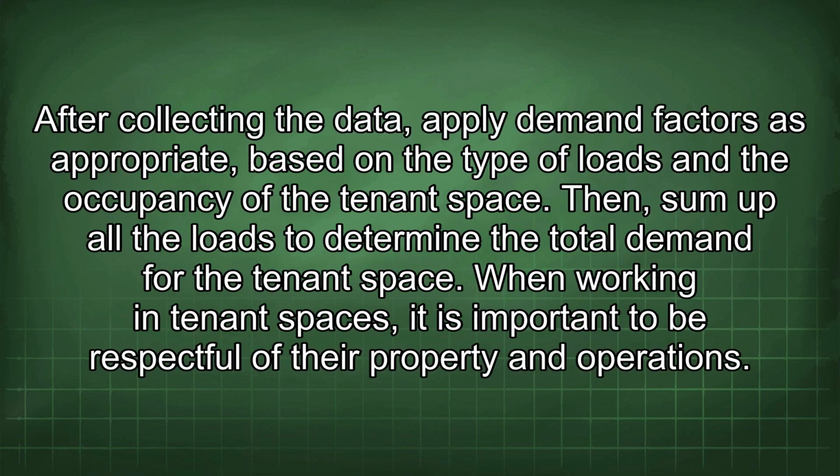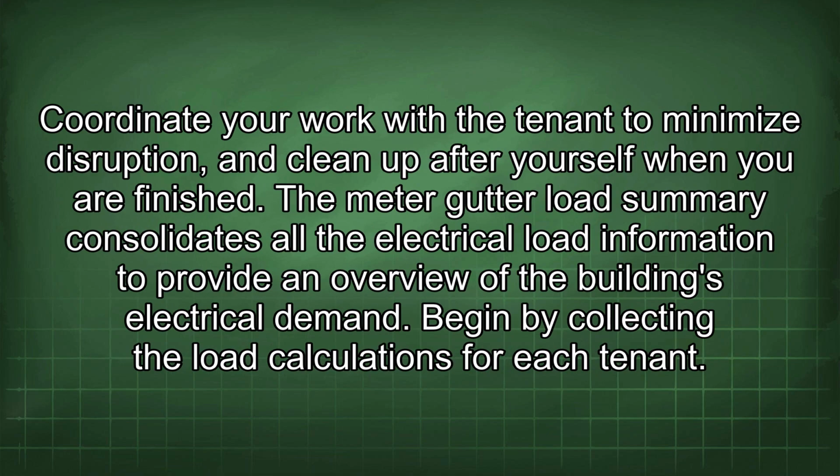After collecting the data, apply demand factors as appropriate based on the type of loads and the occupancy of the tenant space. Then, sum up all the loads to determine the total demand for the tenant space. When working in tenant spaces, it is important to be respectful of their property and operations. Coordinate your work with the tenant to minimize disruption and clean up after yourself when you are finished.